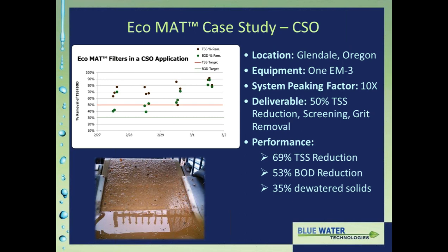And along with that TSS removal, you get a significant amount of BOD removal as well. Ultimately, it would be nice, of course, to hold below a 50 or below a 30 on BOD. And for this particular application, it was able to hold below a 30 BOD with roughly 50+% removal. Now, of course, it's going to depend on the BOD strength of the influent water going into the system.